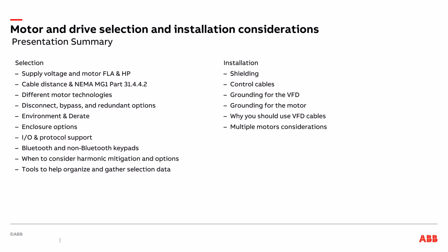ABB has tools to help organize this information with our VFD schedule as well as our product configurator. We have also reviewed the important installation considerations for both the drive and motors, including shielding, control cables, grounding for both the VFD and motor, as well as why you should use VFD cable and what to consider when selecting multiple motors.